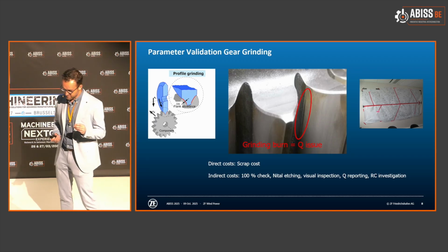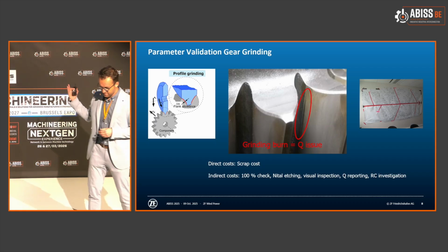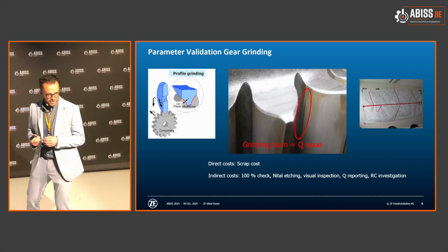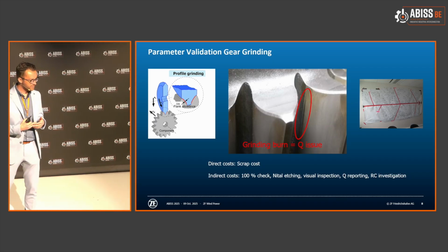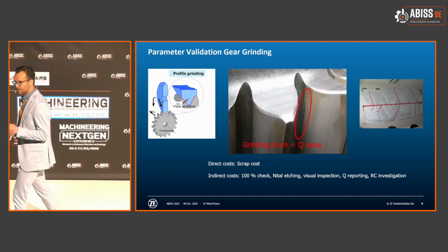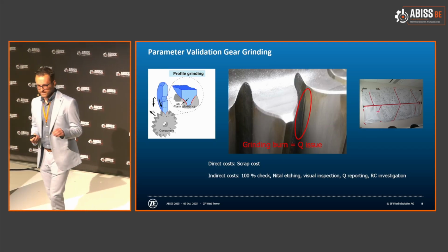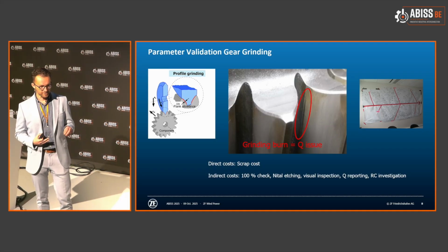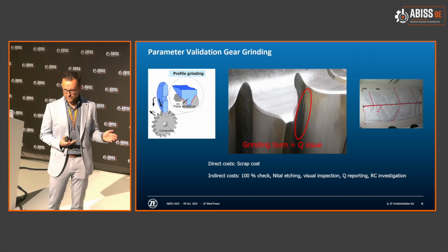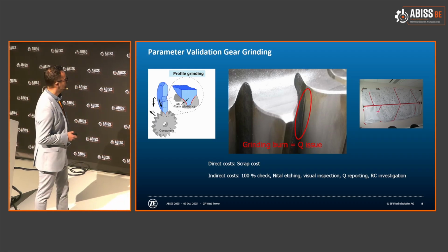And when there is a production issue or an issue in the gear grinding process, you can have a black mark. Is it visible? Yeah, it's visible. A black mark on your tooth profile, which is called grinding burn, which actually changes the material properties of your steel, making the steel more brittle, and therefore it cannot handle these high loads anymore. So this is a very important thing.